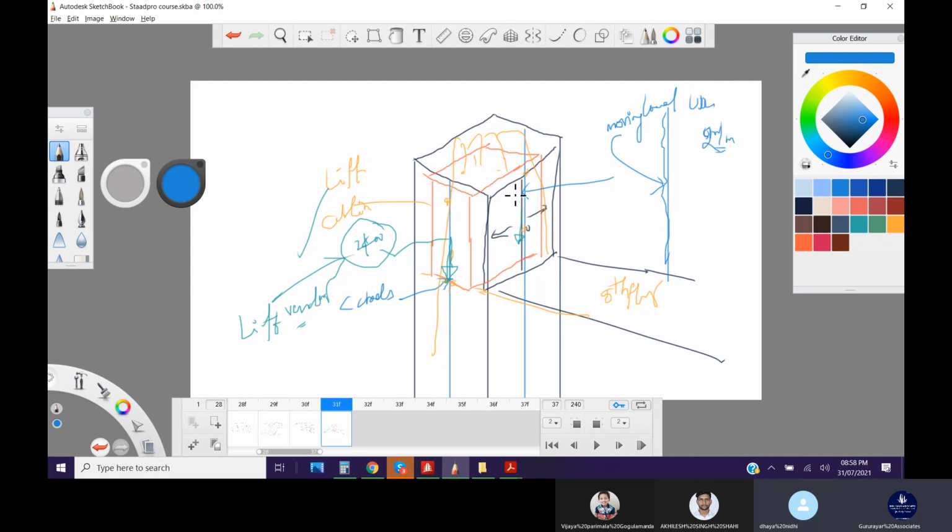So the moving load we apply in this channel as a UDL, and the stopping load as a joint load on the shear wall. But this channel we will not design. The channel will be designed by the vendor. Whatever the moving load may be, it will be taken care of by the vendor. The vendor will apply the moving load, and the sizing of this channel will be supplied by him. We are not required to worry about this.